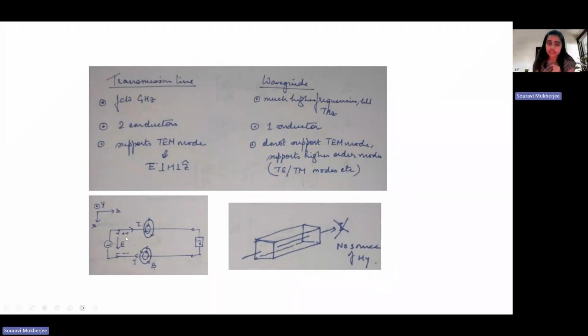And because you have two such positive and negative terminals, and then you have two conductors, there can be a capacitor between these two. Okay, and no wire has zero resistance, so they can have some finite resistance. And if there is some resistance in parallel, it can be considered as some conductances. So that gave us the idea of the distributed circuit parameters. Okay, and this is how typically it looks like.